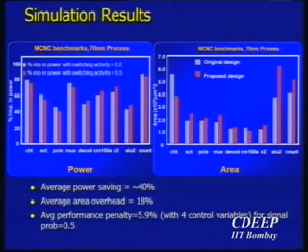Yes, actually, in fact, it does to a certain extent. There can be a long discussion on asynchronous versus self-timed, and that's a traditional discussion that people have. In a lot of cases power can increase, but I'll give you an example of a recent paper that we have in JSSC. The idea was, if I really do very low voltage operations, down to about 300 to 200 millivolts, there you have a large amount of variations, and leakage also becomes the dominant factor.